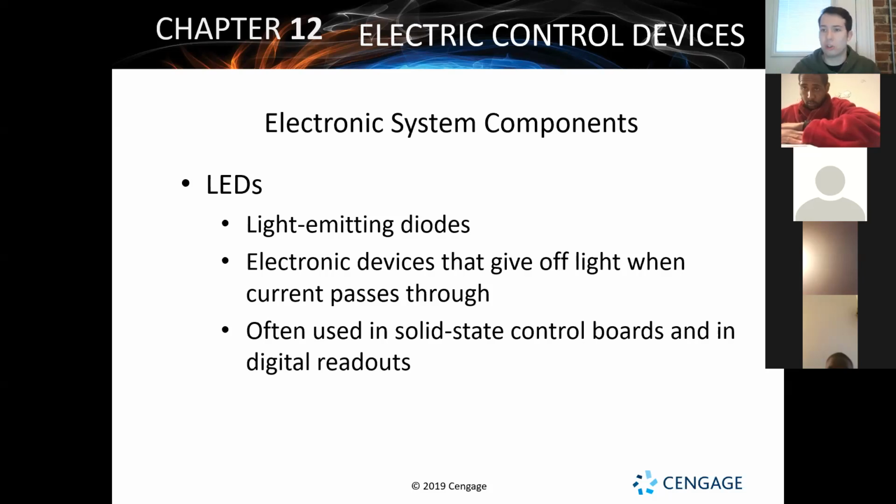So you look on the control board panel, on that cover that you pull off, and on the inside or the outside of it, it'll have a list of error codes. For these modern systems, it's really common that the error codes are destroyed, or you can't read them, or you can't get to them. All you've got to do is go online, look at the model number, look at the manufacturer, find that information, and that'll actually give you those error codes as well.